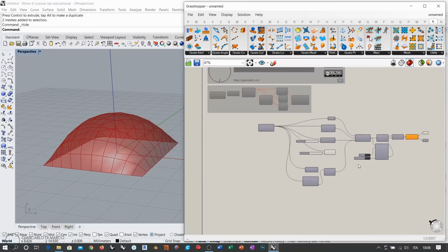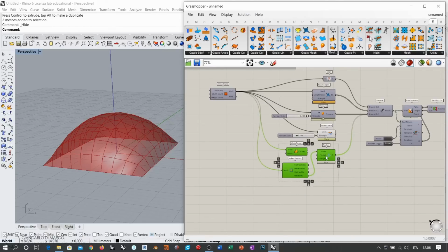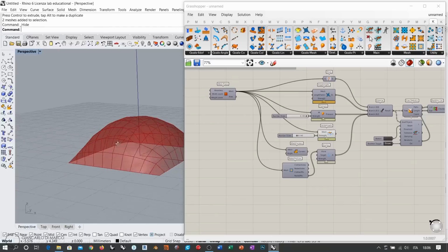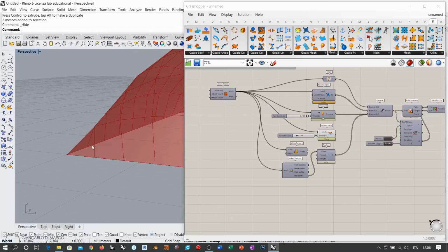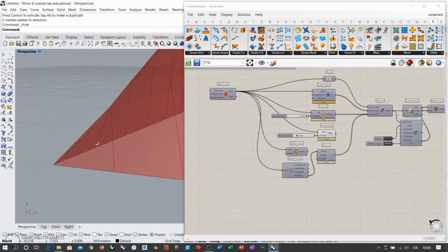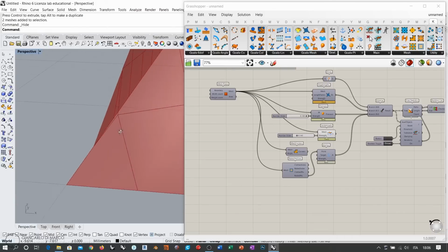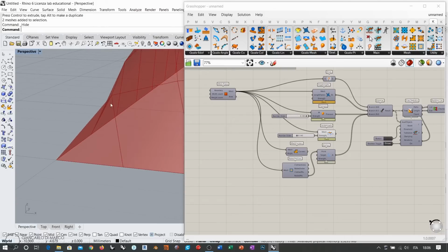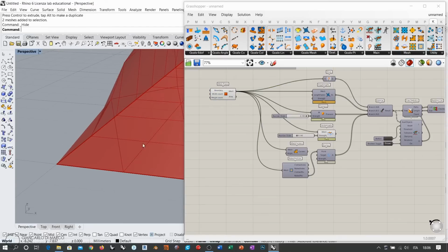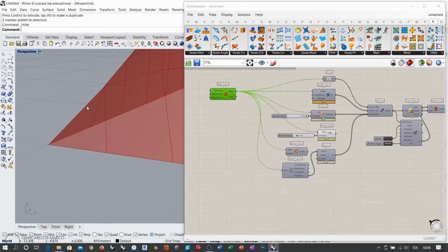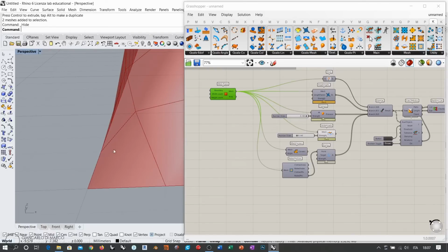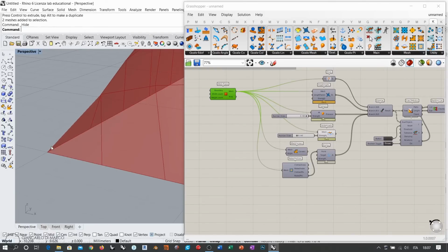I told you that we were going to conduct some topological analysis in case of working with pressure, and this is the moment, right? So if you take a look at these vertices, at the corner vertices, you see that this one is behaving somehow good, right? So you can recognize that there is a diagonal here, which is actually non-visible and non-present in the original mesh. The original mesh only has this quad here, right? But when the mesh deforms, this diagonal edge starts to be visible.